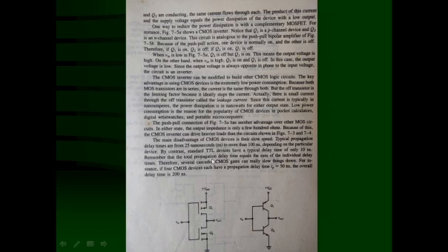Remember that the total propagation delay time equals the sum of the individual delay times. Therefore, several cascaded CMOS gates can really slow things down. For instance, if four CMOS devices each have a propagation delay time Tp equal to 50 nanoseconds, the overall delay time is 200 nanoseconds. So the speed of operation of CMOS is lower. That is the disadvantage compared to TTL.